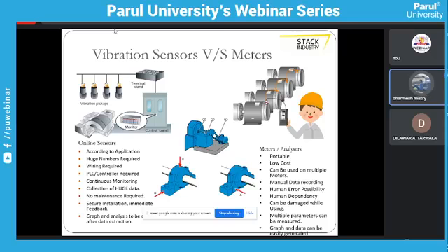They cost around 10 to 12 lakhs per device, but you can check very properly. All the motors and everything can be totally analyzed, whether the back end bearing is gone or the front end bearing is gone, or whether there is a mechanical looseness, or any other problem. It can be analyzed using a vibration analyzer. And vibration meters are low cost devices. A vibration meter will cost you around 30-40,000, but you can check multiple devices with that.